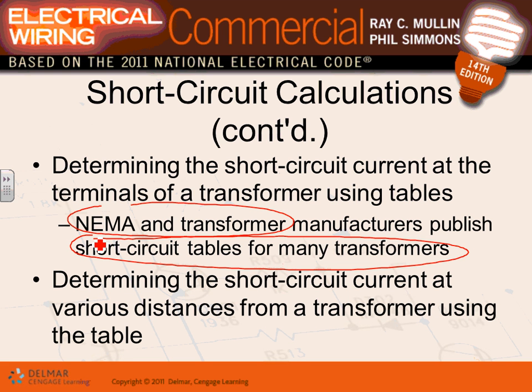Where's this short circuit coming from, Brian? It's coming from your company, Xcel, right? Because Xcel is pushing power into your building. To power that building, if you short that building, phase to phase, that power has to go somewhere. Where does it go? It's going to burn your building, basically, instead of powering it.